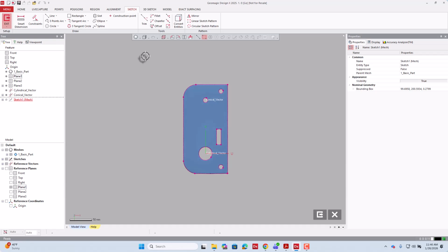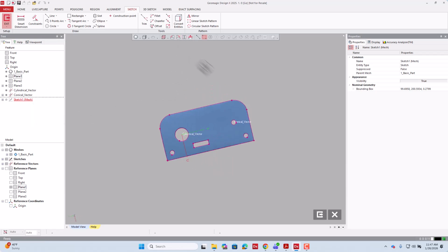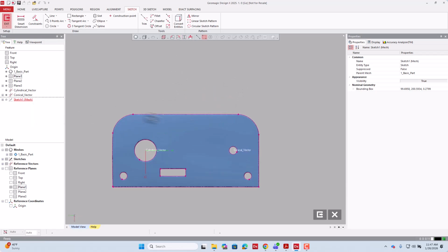When you click on OK, you'll see that the software has opened a sketch palette. Here you have the sketch palette with all the basic sketching tools like line, rectangle, slot, circle, arc, etc. You also have your body and trace here. You can hide the mesh by clicking here where you see my cursor.